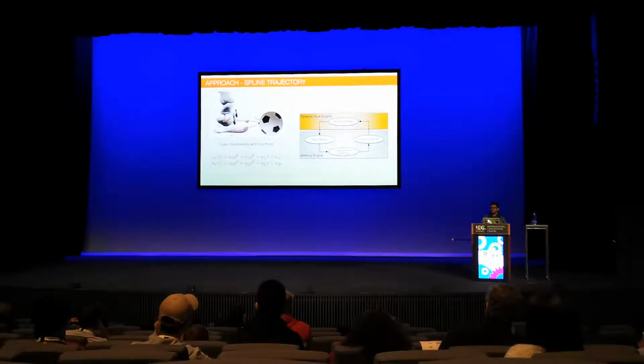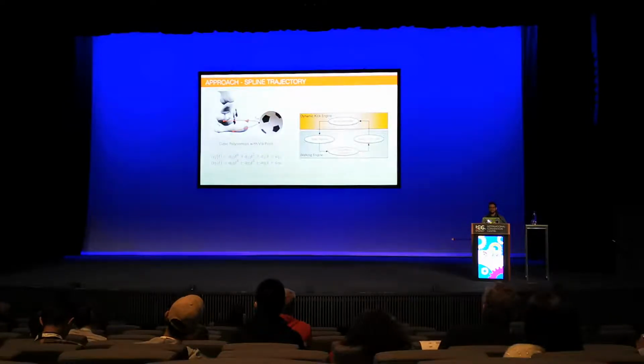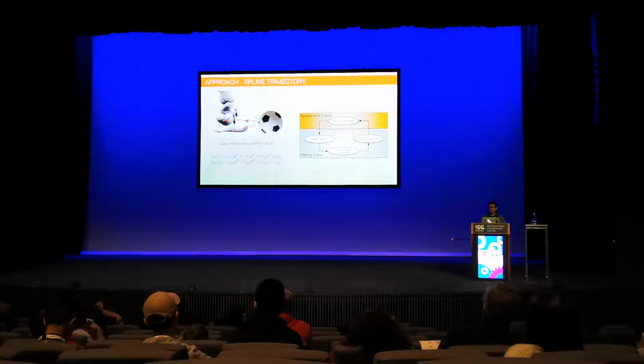So when the agent sends a request for walk kick, the motion request is received by the step planner, and the step planner chooses the next steps of the gait cycle that minimizes the amount of time to reach the reference trajectory, which is dictated by the model, which in this case is the linear inverted pendulum model. Therefore, if the agent requests a kick while the robot is walking, the step planner has to plan for the kick motion while guaranteeing a stable walk.